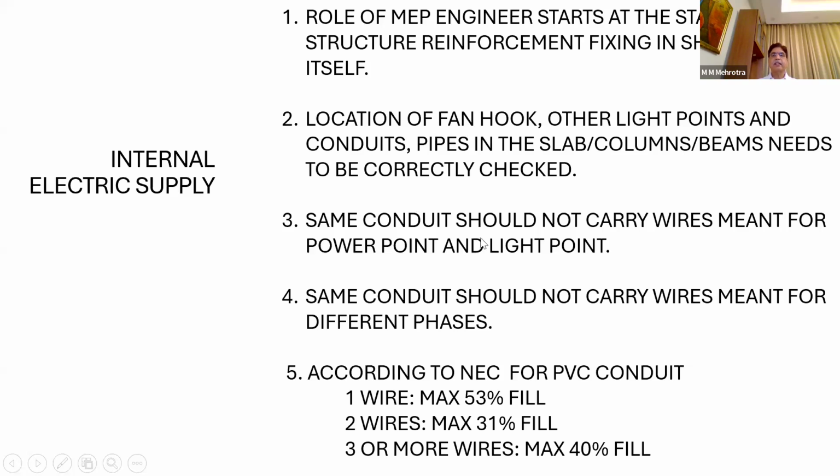Now next is conduit. You see that there are many wires inside it. There will be power wiring and light wiring. The same conduit should not carry wires connected to power points and wires connected to light points, for the obvious reason which you understand.